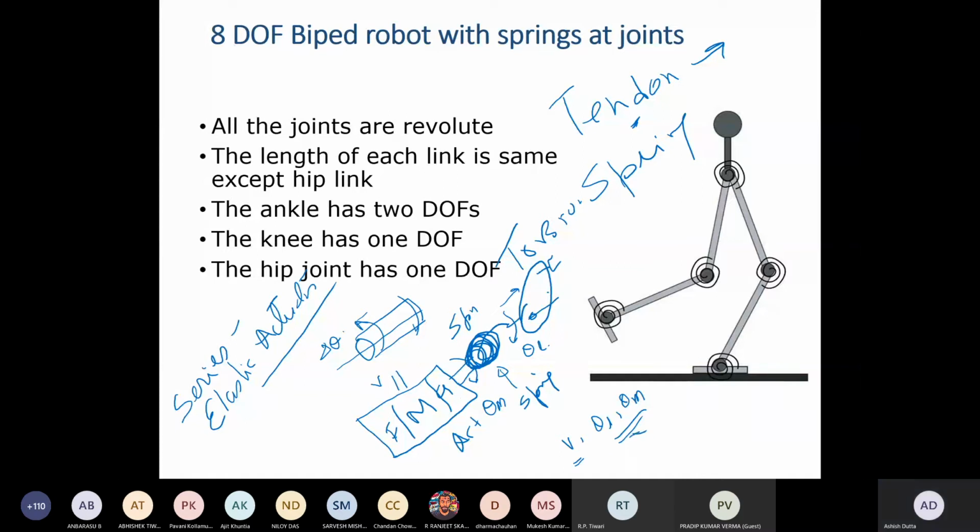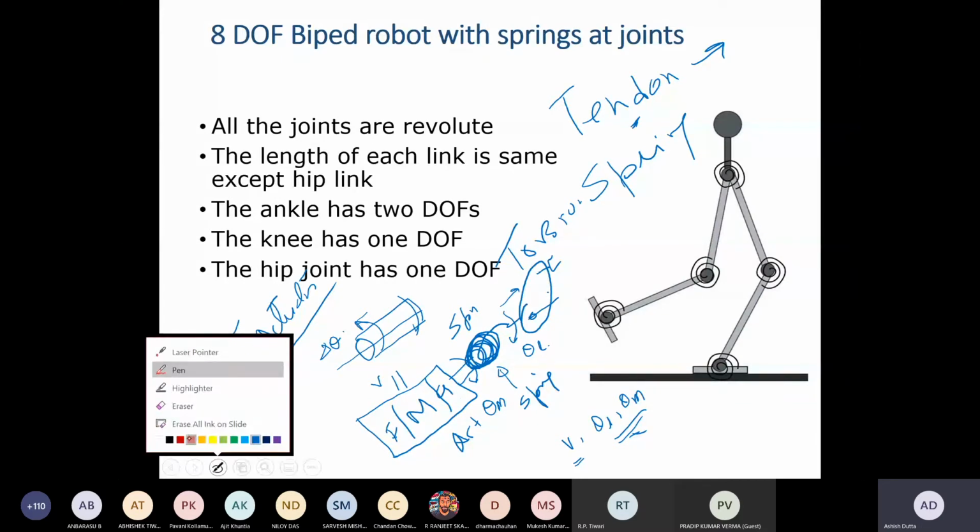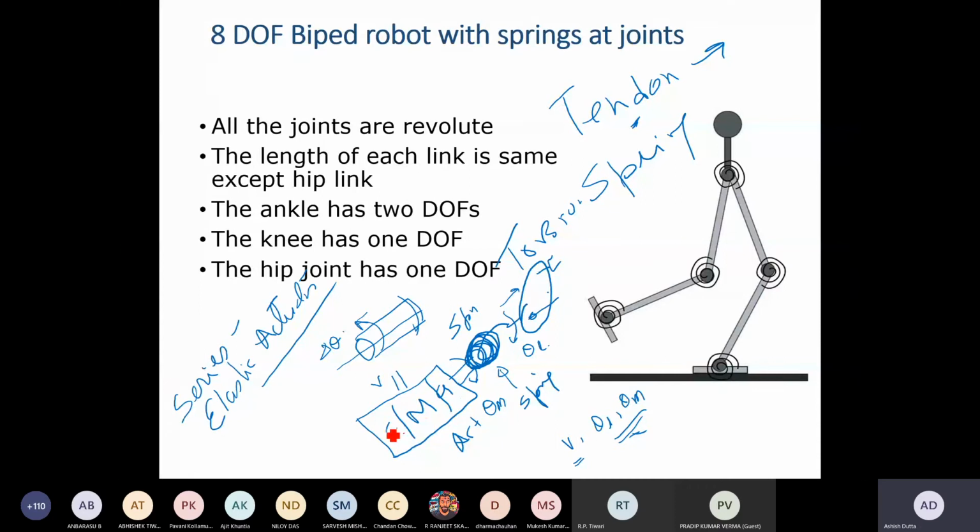So in terms of control, this is what happens. If you start putting something flexible in there, it will make your control more and more difficult, which means it is going to start introducing vibrations. It can lead to instability. So what is done is basically they put a sensor onto the other side also. There is a sensor here already, an encoder in the motor, but they put one more sensor here and then use a backward loop.